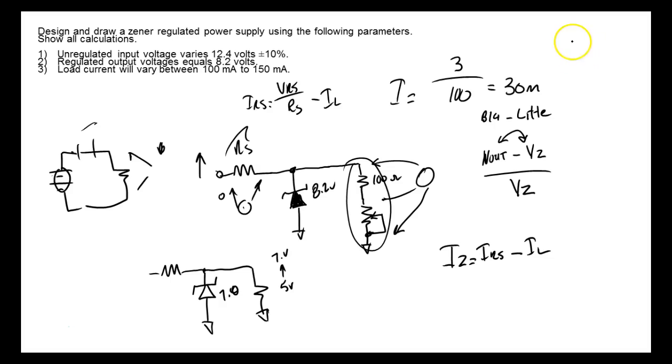We use them back to back, where we come over here in an AC circuit and we want to do the same thing. They'll put back to back Zeners. They'll just connect them together like this. And this protects an AC load, right? You understand? So if it ever exceeds the Zener voltage, it'll clip off. It'll clip off the top of the alternation, or it'll clip off the bottom of the alternation. So we use Zeners in all types of that.